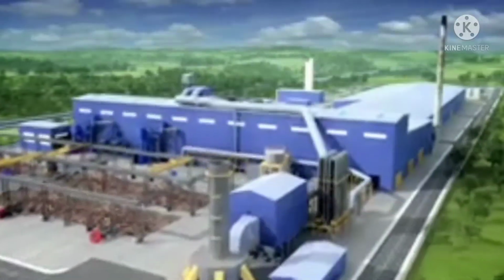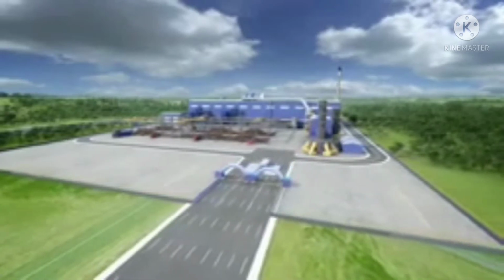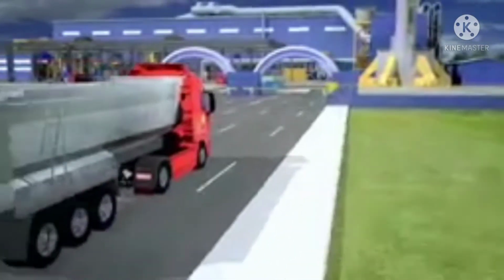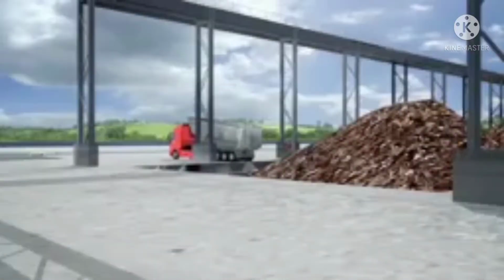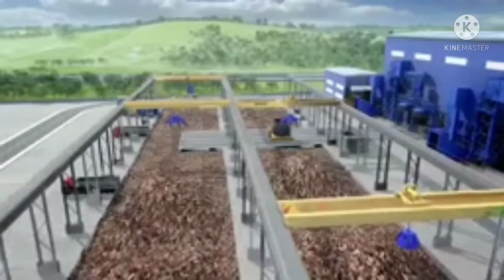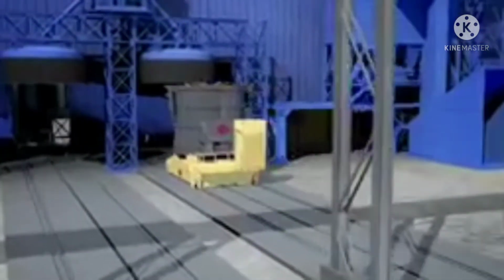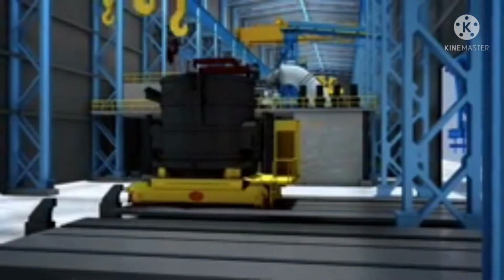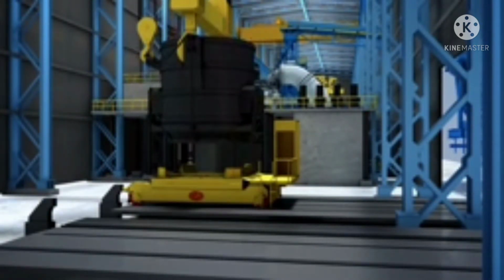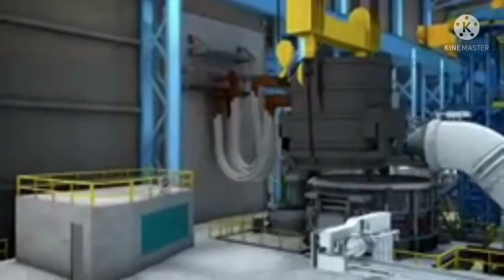Steel making process. The steel making process especially needs raw materials like iron ore, lime, and coke. Once they have been taken from the mining field, they go directly to the steel plant where the process is done. As iron is the main component of steel, it firstly needs to be made. Iron ore, lime, and coke are placed into a blast furnace and melted. The resulting liquid, known as molten iron, is then formed. Molten iron contains around 4% to 4.5% carbon, which tends to make metal brittle. It needs to be eradicated.